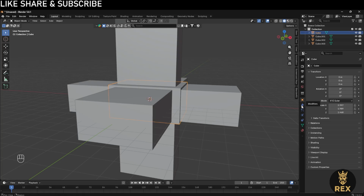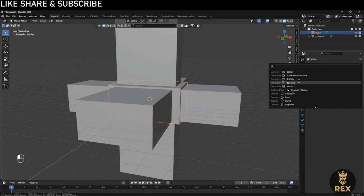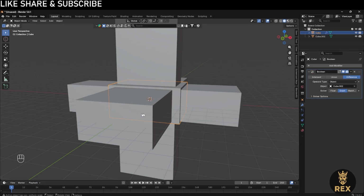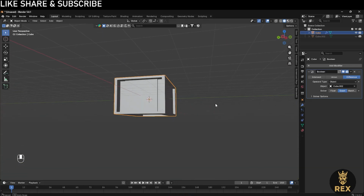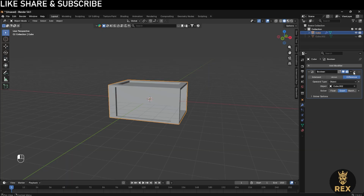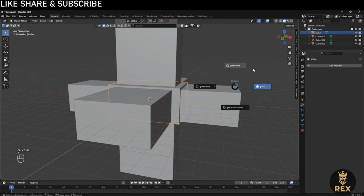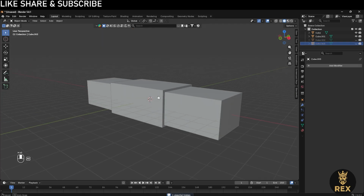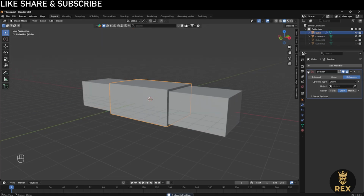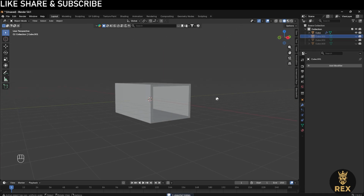Now what we will do is join these. I will add a modifier called the Boolean modifier. Now you can see this work has been done, but I do not want this type of result. So I will undo this joining and we'll do it one by one. First press H here and here, then here press Boolean, then H. Now I got the result which I wanted.